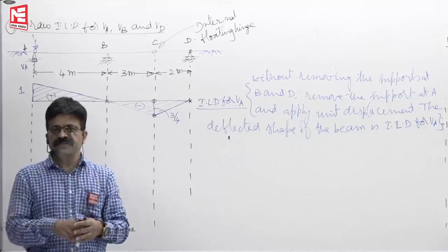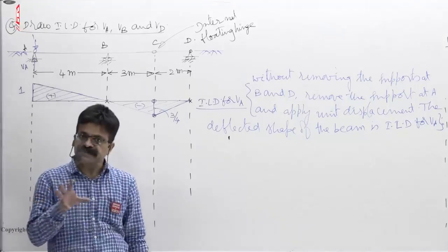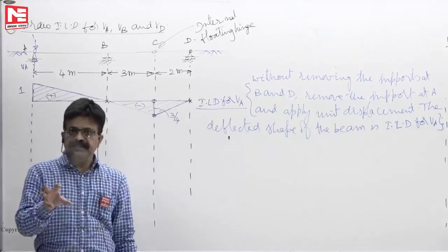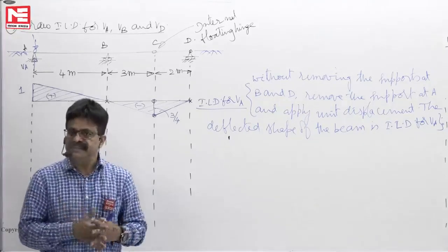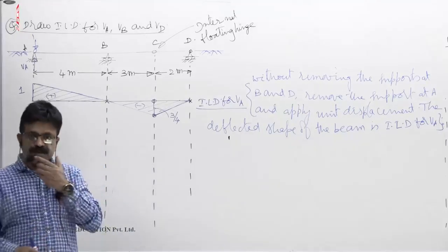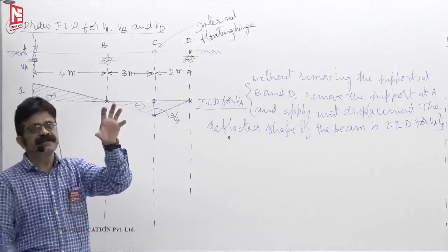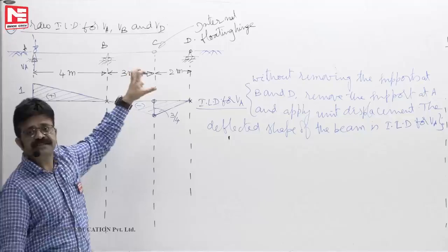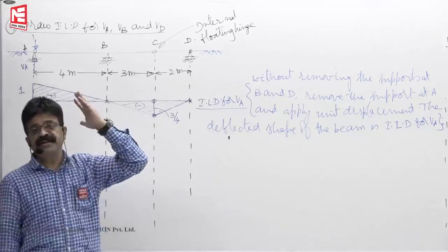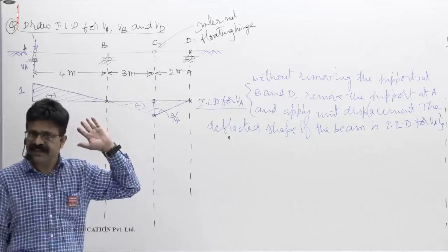Fatigue means what? Any material subjected to reversal of stresses loses its strength. The property of losing the strength, we call it fatigue. So it will fail quickly. So when you are designing that pin, suppose that you are designing this bridge for 100 years, then you have to say in 100 years maybe it is 10 million times that stress reversal can happen.